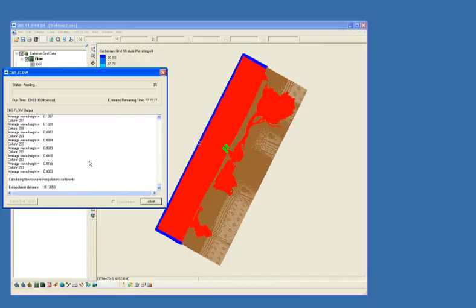It's a little bit hard to describe. I may be able to find a PowerPoint that shows that a little bit more, and I might bring that in tomorrow. So calculating the coefficients for the extrapolation is a one-time thing. As long as you don't change your flow grid or your wave grid, then these values will only have to be calculated once. The next time you run, it will actually find those written in the directory and use those. And this can take a little bit the very first time to run this.